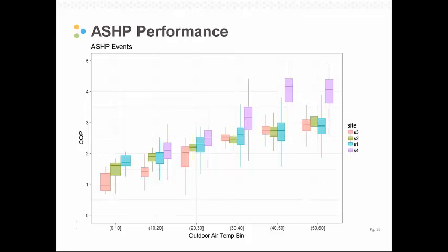That has a lot to do with the airflow that's achievable and some of the operating conditions at that site in particular that let it be extra efficient. But the big takeaway here is that from the point where the heating kicks on in full at around 50 all the way down to that changeover point at 5 or 10 degrees outside, when the heat pump is running on its own, it really matches up with those specifications supplied from the manufacturer. And this is really encouraging.